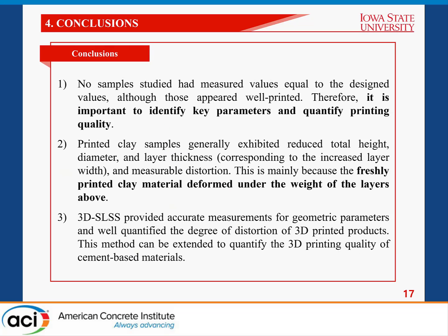So here are the conclusions. None of the samples studied had measured values equal to the designed values, although they appear well printed. Therefore, it is important to identify the key parameters and quantify the printing qualities. Second, printed clay samples generally show reduced total height, diameter, and layer thickness, and measurable distortion.